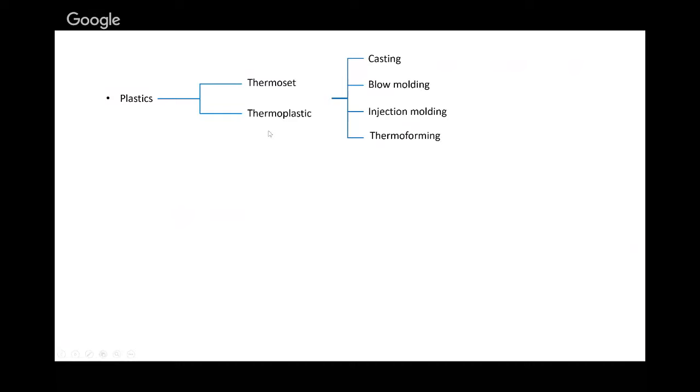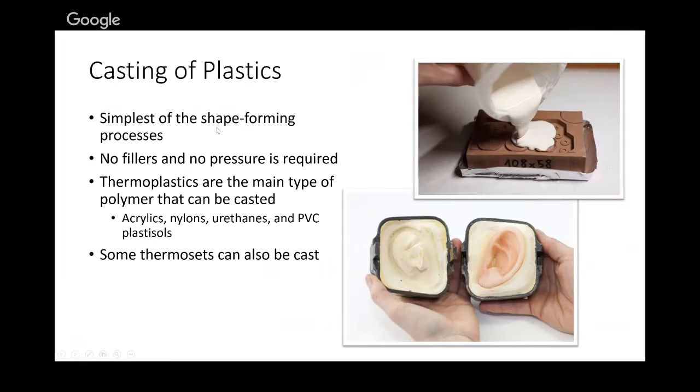You heat it up and it melts, and you do something with it. The 3D printers, the filament printers, use thermoplastics. A hot glue gun is another example. Thermoset polymers or plastics are more like your epoxies, your Teflon type materials, where once you make the plastic, once you solidify it, that's it. You can't re-melt it with temperature. Think of set meaning that's permanent, and plastic meaning that you can reheat it and it will melt again.